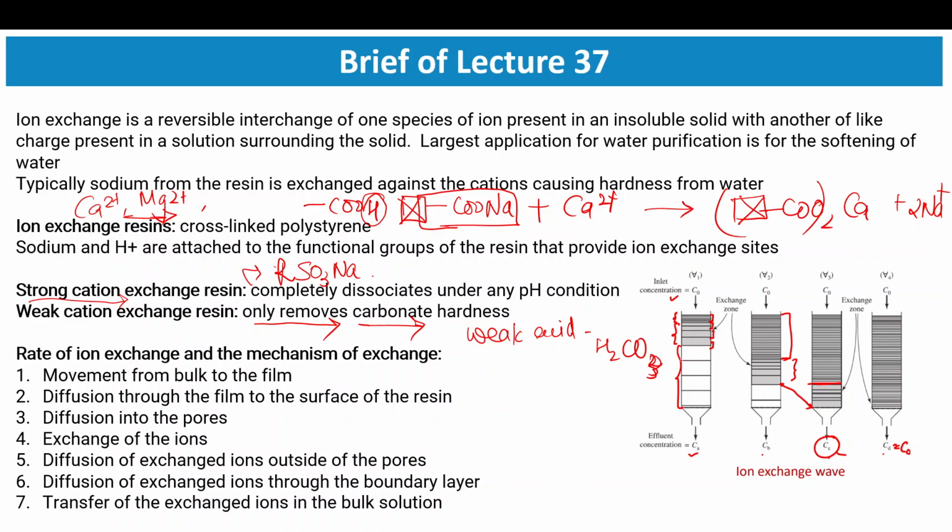So this is a weak acid, and the salt is formed because of a reaction involving a weak acid. You can say it will be more effective in removing the salts or the hardness corresponding to the weak salts or carbonate hardness, because it contributes from CO3 2- or HCO3-.